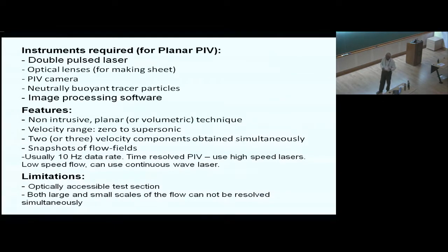So 3D PIVs are coming now. Then you illuminate a volume. Then you will need at least 3 cameras to get the flow field. And even there, the volumes are relatively small.